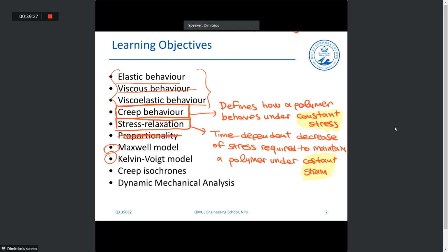To answer something, the Tg, of course. No, the melt flow index, the melting point, and the glass transition. Indeed, Kayla is right. So indeed, we can obtain information regarding the transition temperatures, that is mainly the glass transition and the melting point.